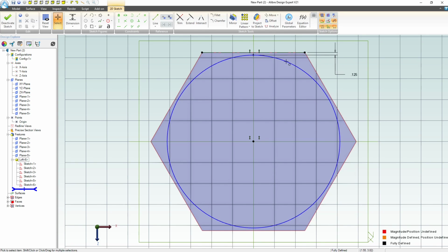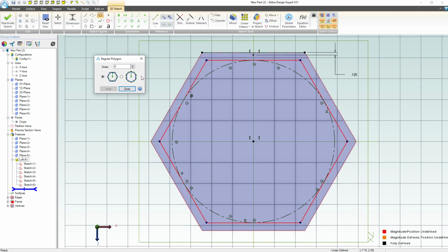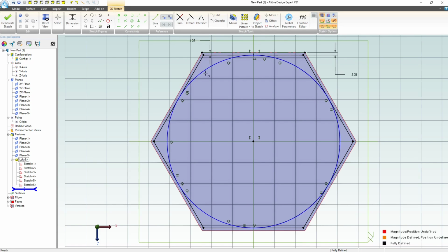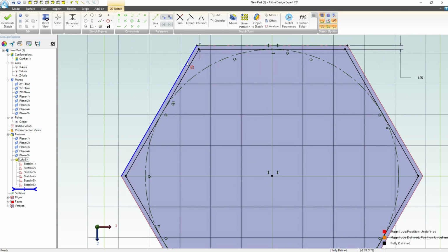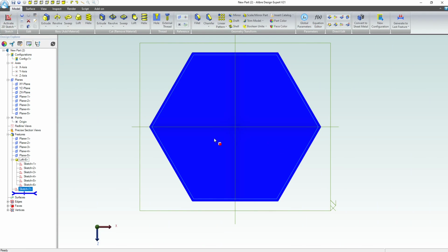And you know, I'm thinking a hexagon pattern might work pretty well. So let's change this here. I'm going to make a new hexagon. We'll apply that. Make sure that we are horizontal here. Change my mind mid-video. I do that more than you know, I just don't mention it usually. Let's go with 0.125, right? So we have 1/8 inch thick. Pretty thick. Everything else looks good. So let's deactivate that.